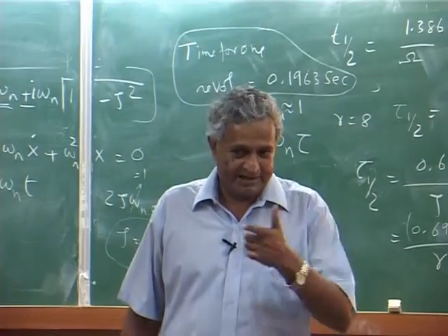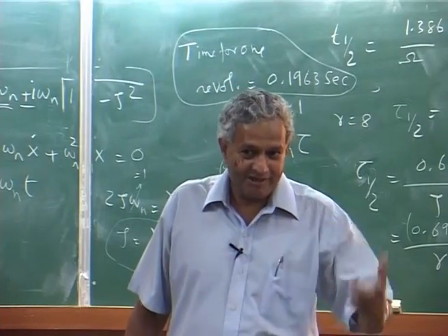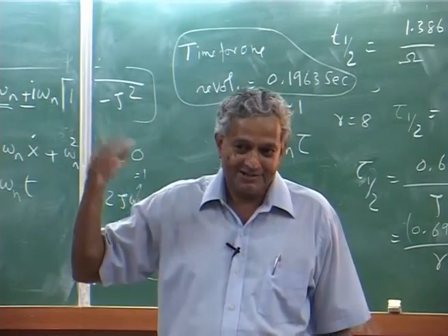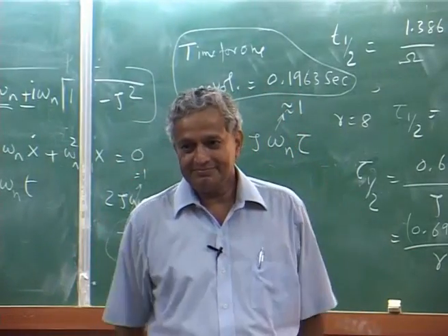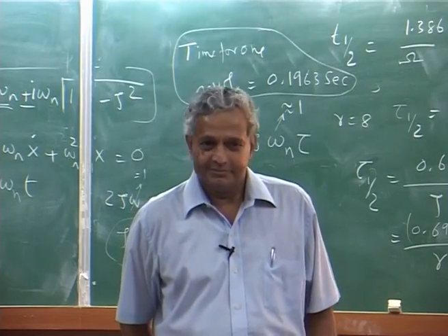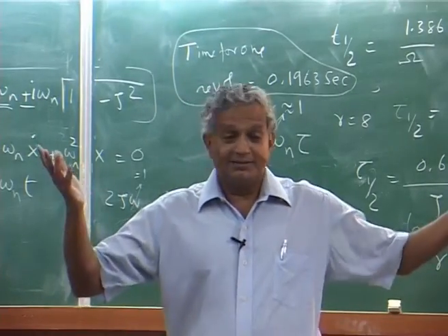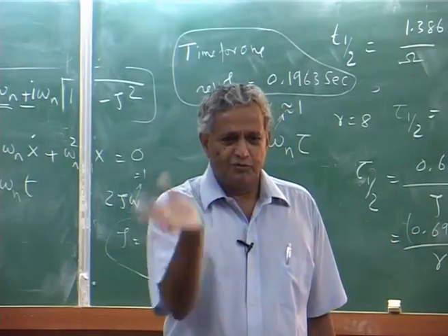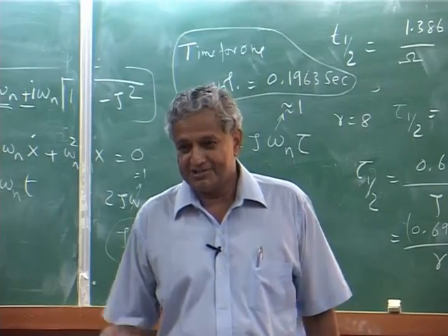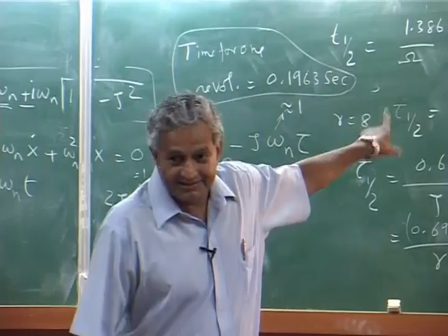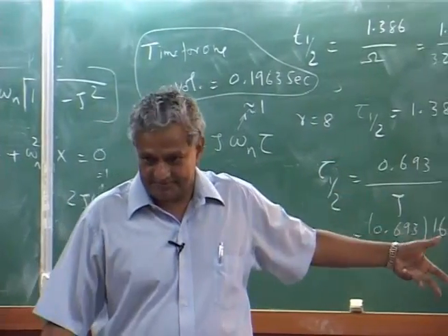Now, when you really solve the flight dynamic equation, you will not have flap dynamics in your model, you will only have fuselage equations. And where is the blade dynamics gone? It is taken as change in force, instantaneous change in force. That is because of this quickness.